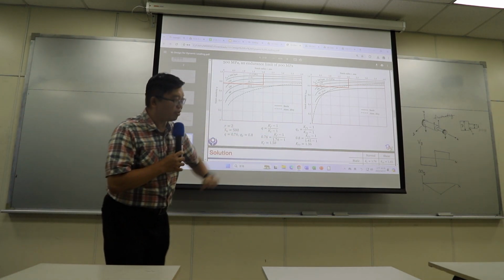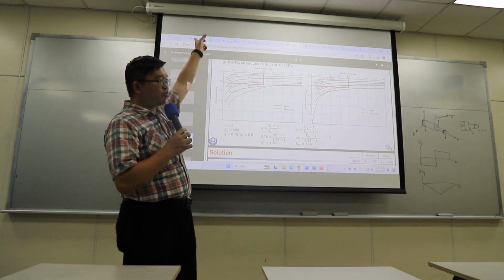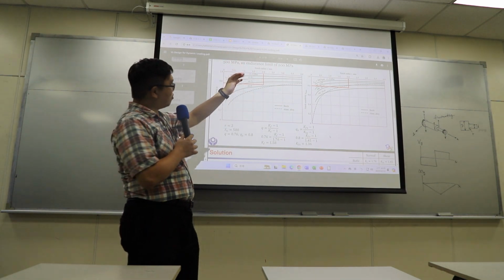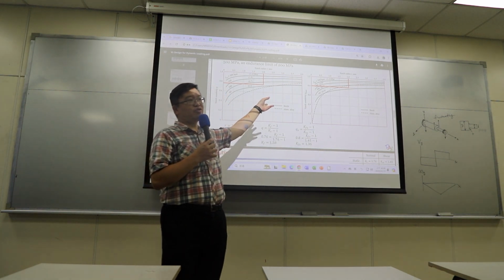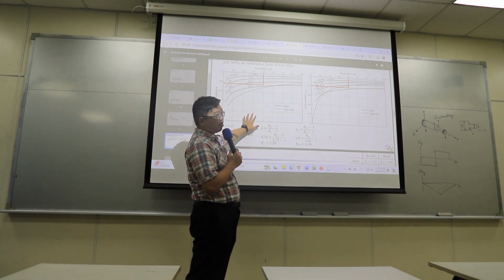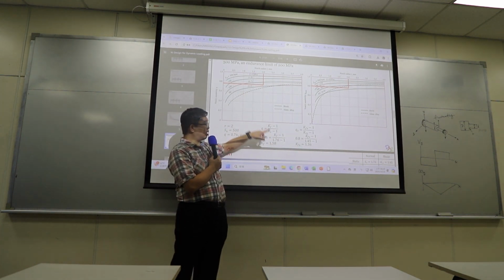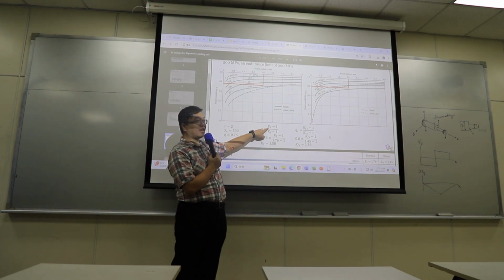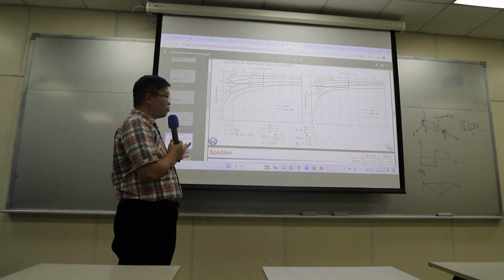And since in this example, it's just normal stress. And in the previous slide, we have K for normal stress and static. Now, if you have notch sensitivity Q, you can use it to compute for the K for normal stress and dynamic loading using the equation right here. Because KT can be found in the previous table. Q can be found in this table. And KF can be determined. KF will be the stress concentration factor for dynamic loading.